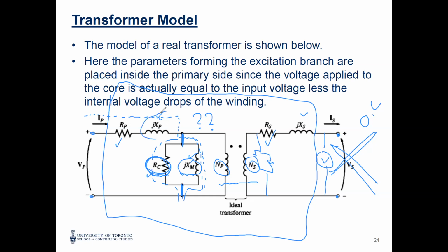You will find that there is a leakage in the primary, and there is heat in the primary. You will not see any heat at the secondary because there is no current flow here. It's open circuit. Even if you put a voltmeter, the voltmeter has very high resistance, so the current will not flow and no losses. So this is the reason we put this one in shunt.